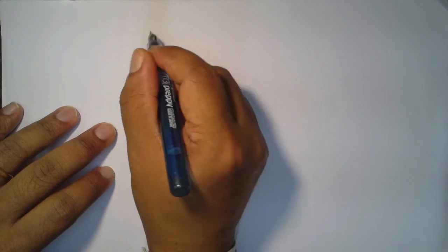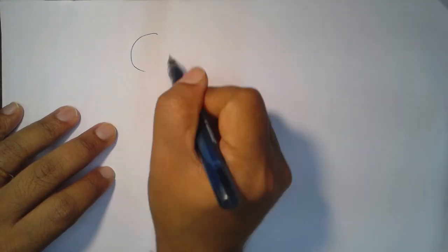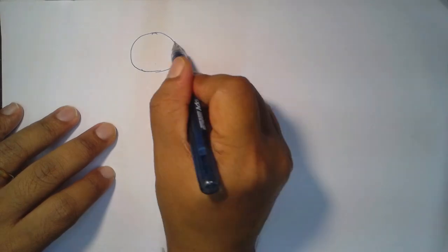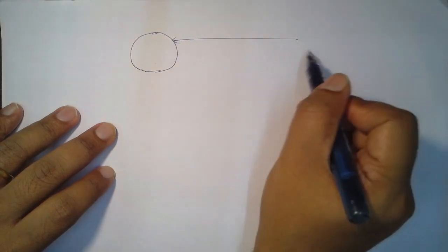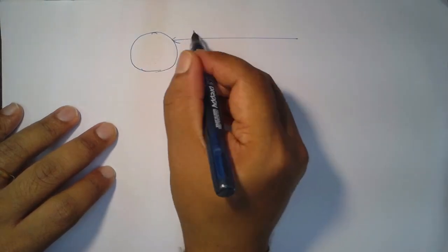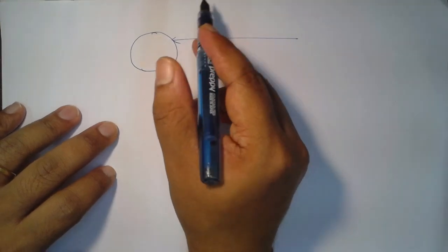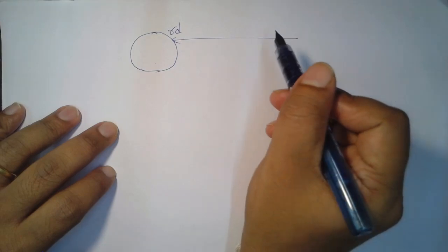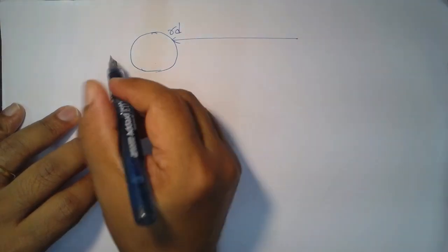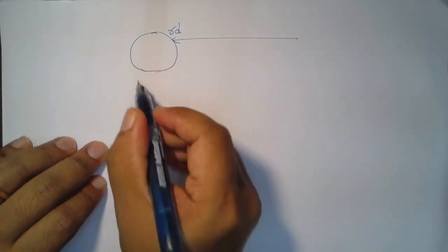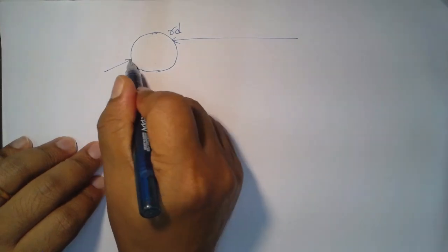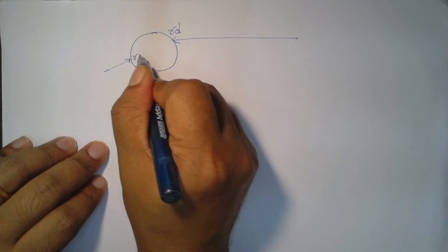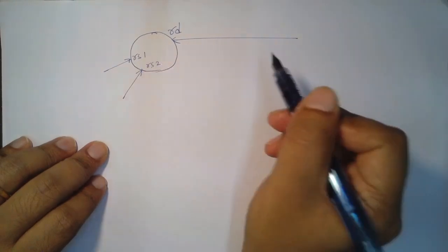So, if I consider this control logic as your stall logic, it will have feedback from earlier stages about their destination registers. Destination registers we generally denote by RD, and then from the decode stage we will get the source registers, basically RS1 and RS2, right.